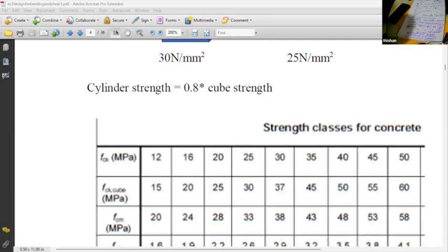But you know, in pre-stress concrete, why do you need fly ash? You don't need it. Why? In pre-stress concrete, the section should be as small as possible, as thin as possible. If the section is thin, if you want workability, you can use about 10% fly ash. But otherwise, to cast pre-stress concrete sections, you don't need fly ash. Fly ash is needed to avoid DF. So if the sections are thin, pre-stress concrete, you can't use massive sections, then it's not economical. So in pre-stress concrete, what is economical is sections as thin as possible.